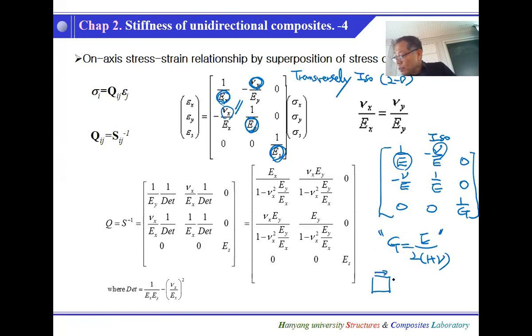One simple way is to consider pure shear stress or strain relations. And this is exactly the same as tension and compression. Say this is sigma in terms of magnitude. So this is minus sigma, this is plus sigma. So why are these shear stresses identical to this normal tension and normal compression at 45 degrees? This is the 45 degree.